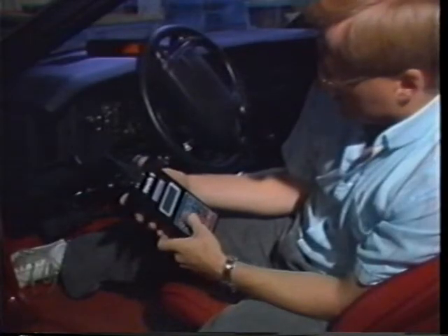If too much force is applied to the ECM during the test, you may cause an ECM reset or glitch, creating a momentary stall, miss, check engine light, or loss of serial data, or damage which will cause a failure at a later date, or an immediate ECM failure.